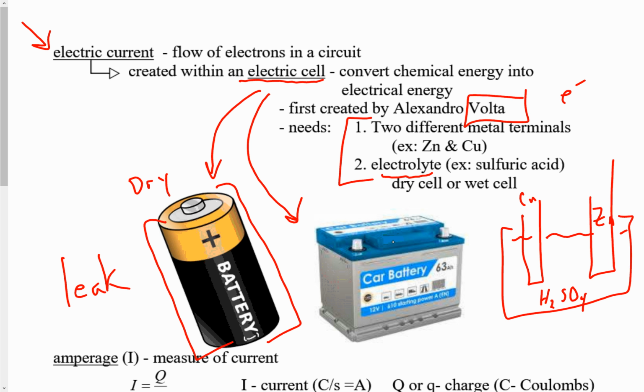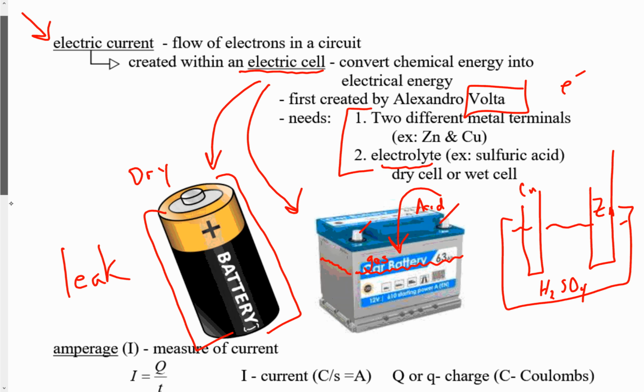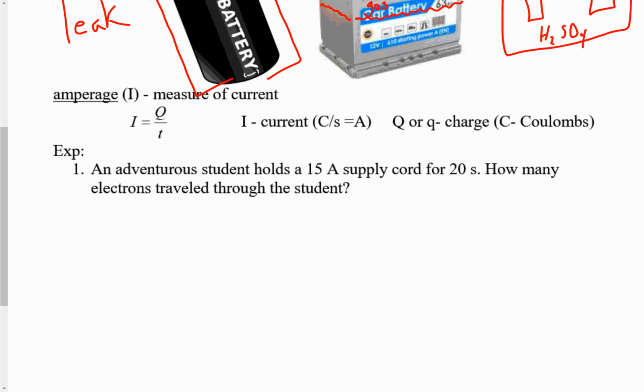I guess I'm old enough, I actually remember when you went to buy a battery and you actually got a jug of acid and you poured the liquid into the battery yourself. The only buzzkill about some of these older batteries is eventually the water part of the acid would start to evaporate, and you would get a trapping of gas at the top. That's why you had to be very careful about sparking the tops of these batteries, because you could ignite the gas and blow the top off of the battery, which unfortunately I have done before. So anyway, luckily my back was turned when it actually blew.